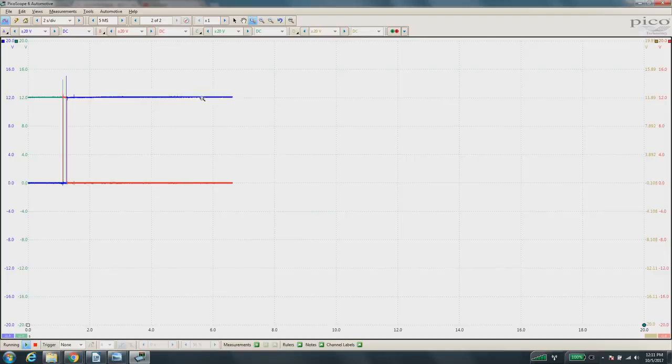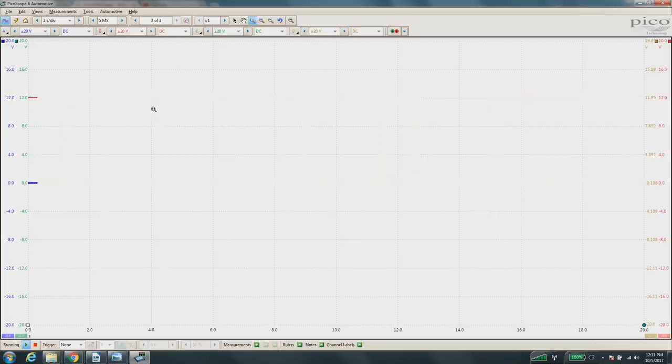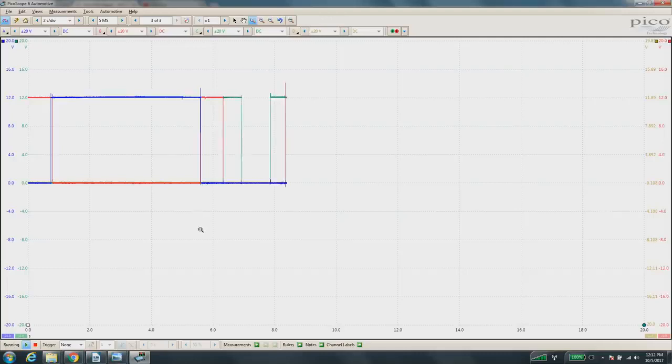Blue trace is high at 12. Let's go reverse. Neutral. Drive. Park. Or sorry, back through the gears. We missed one signal in there, but that's okay. Keep going. All right, and just go through it quickly. All the way down, all the way back up. All right, so we definitely lost drive. Signal must have fallen out.